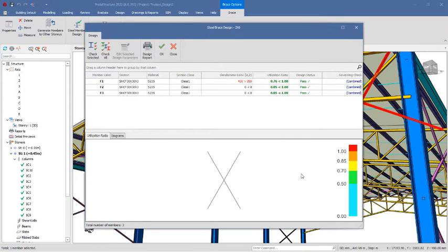So you will notice that our braces have actually passed design as well, but we have a slenderness ratio, okay? But for this, if you split this at this point, and at this junction where these two braces meet, if we have a kind of connection there, it is going to solve this slenderness issue actually. So that is not an issue that cannot be corrected, okay?